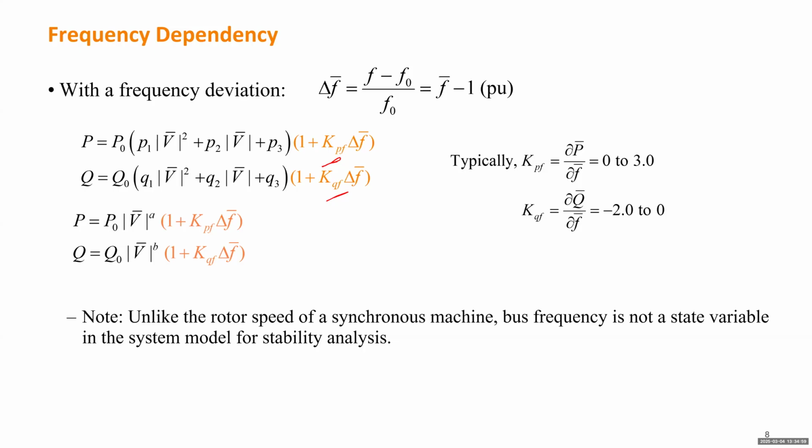So if you draw the waveform of that bus frequency, you can see the frequency suddenly change. There are some spikes on the frequency. That is because of the sudden change of current and voltage on that bus. When you calculate the derivative of that waveform, it creates some singular value or very abnormal value, like a spike. But that doesn't mean the generator has that jump in frequency.